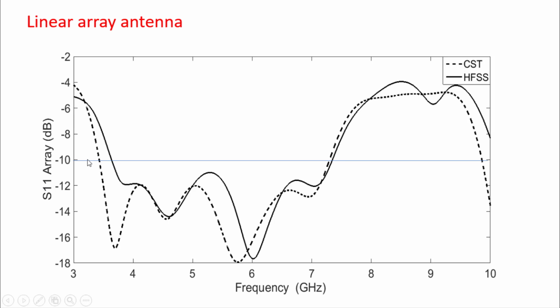Looking at the return loss at minus 10 decibels, the bandwidth is greater than 500 megahertz, and it belongs to 3.1 and 10.6 gigahertz. So in this antenna we verified the FCC condition of ultra wideband characteristic.